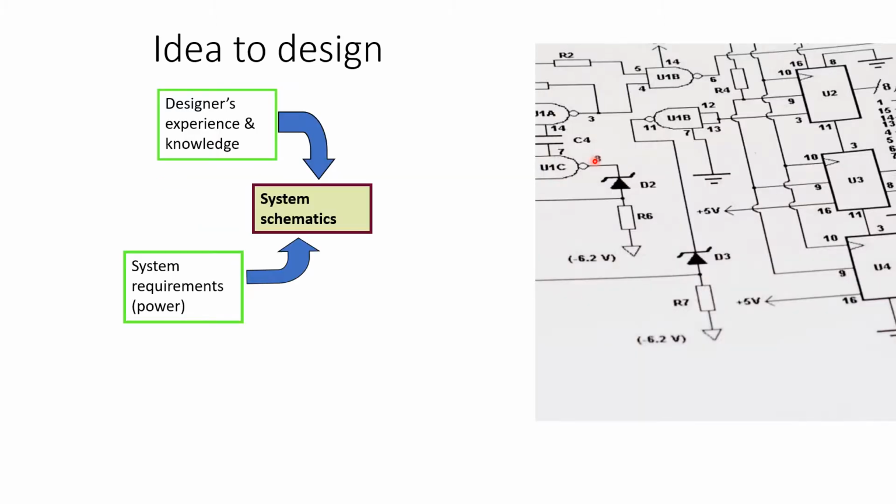So in general, if you are working on electronics, you start with drawing a schematic diagram. A schematic diagram is the diagram that you draw with circuit symbols like diodes, resistors, and some gates over here. In order to do schematic diagrams, you need to look at the system requirements, the inputs and outputs, how things should be processed, and the power requirements, and things like that.